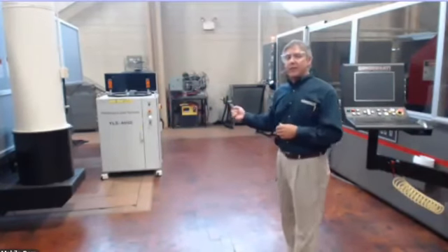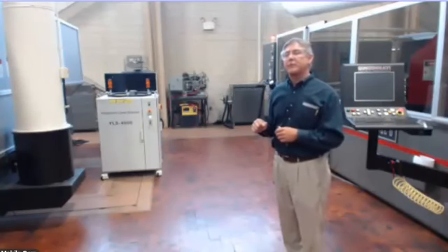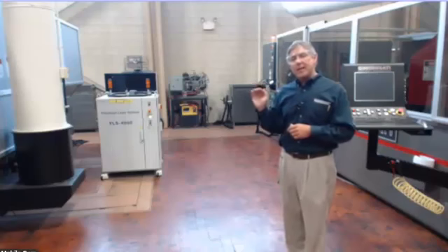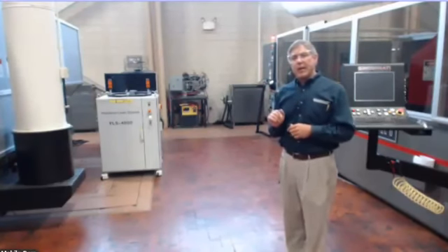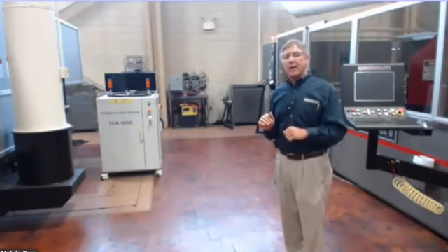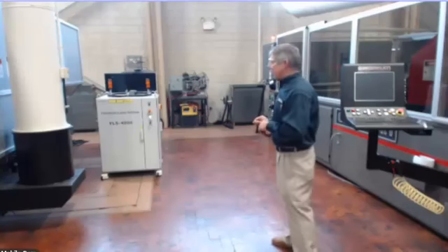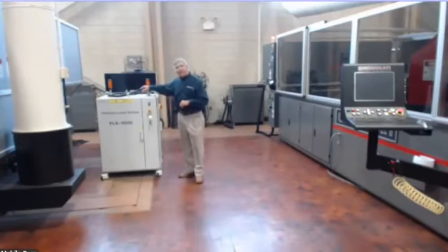Now, getting the laser beam from the power source to the cutting head. That's another big difference between these two technologies. On a CO2 laser, we take that beam out of the laser resonator, send it through some tubes and bellows, off some reflecting mirrors, and direct it down to the cutting head and then ultimately onto the material. On the fiber laser, our beam delivery system is housed inside of this cable carrier.